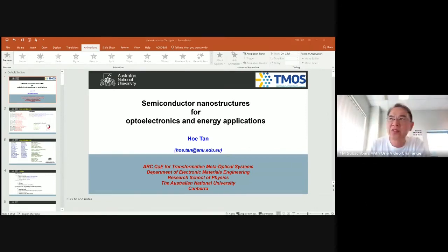This is a 2D material, and we synthesize this boron nitride in my lab, where we can grow wafer-scale, large-scale material. I'll show you a few applications, such as surface enhanced Raman scattering using the HBN as a passivation layer, single photon sources coming from the HBN, and also using HBN as a template for growth for flexible devices.